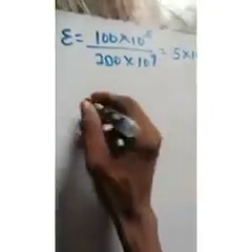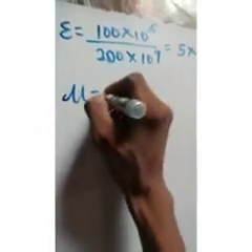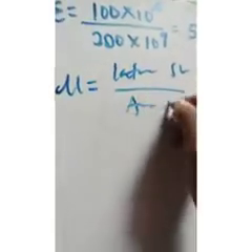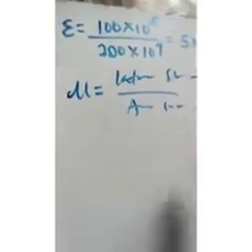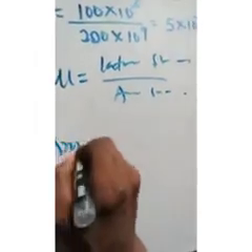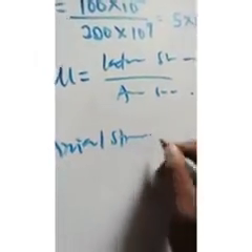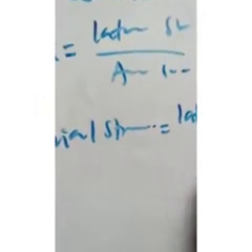So I can solve for the Poisson ratio now and say Poisson ratio is my lateral strain over my axial strain. Don't mind writing since you know the formula. Now to get my axial strain, my mu will come here, so I'm going to have it as the lateral strain over my Poisson ratio.